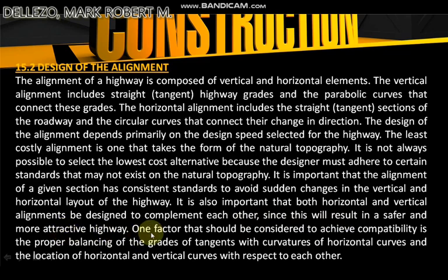One factor that should be considered to achieve compatibility is the proper balancing of the grades of tangents with curvatures of horizontal curves and the location of the horizontal and vertical curves with respect to each other.